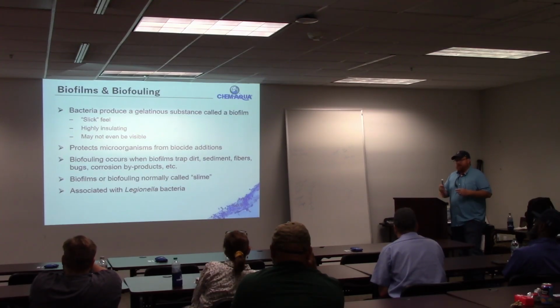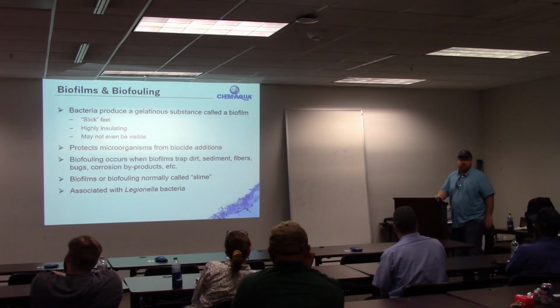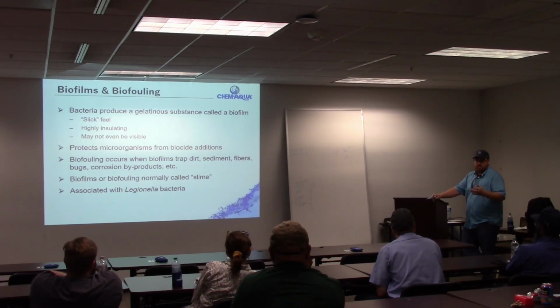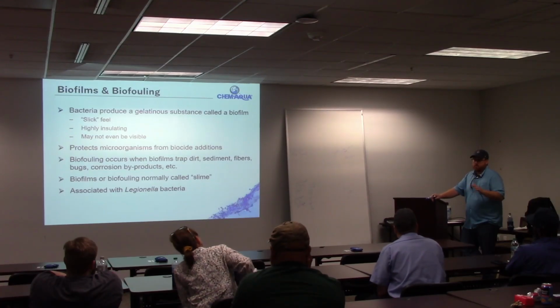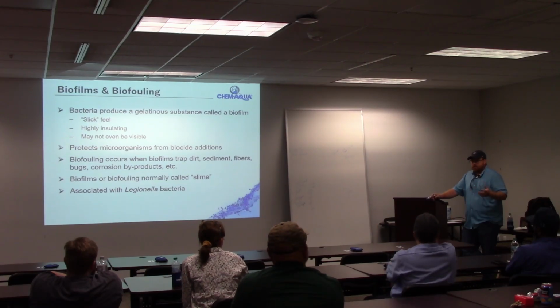You can also have, with dead legs, a little bit of burping sometimes, where the water is trying to make its way down there, but it can't. It will burp up some of the junk that's sitting in a drop leg or a dead leg. So those are things that, especially in healthcare facilities, it's really important to have not only a water management plan, but also have somebody come in and do a Legionella assessment. Just look at the whole facility, top to bottom, all the piping, identify if you have dead legs, identify offline systems, offline piping with no flow for periods of time, things like that.